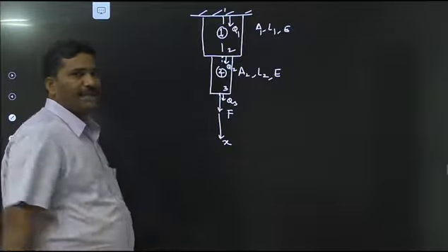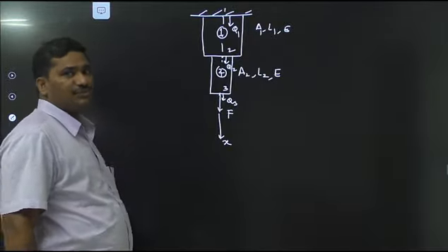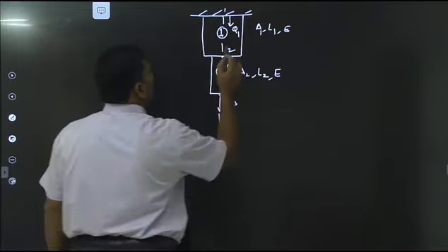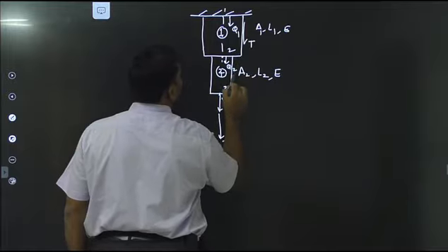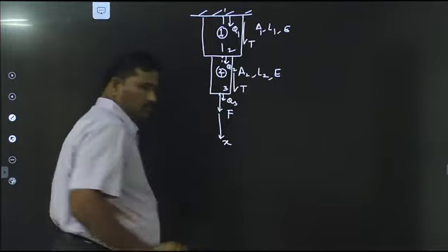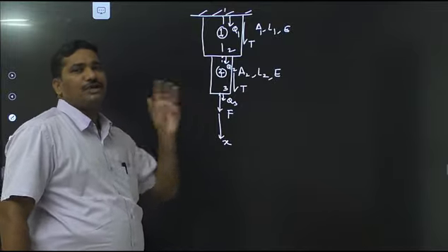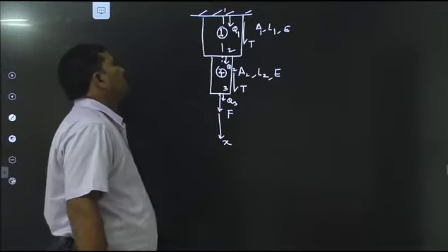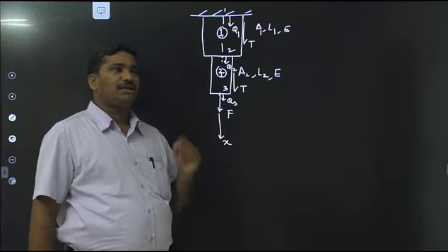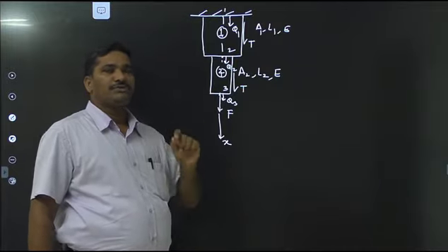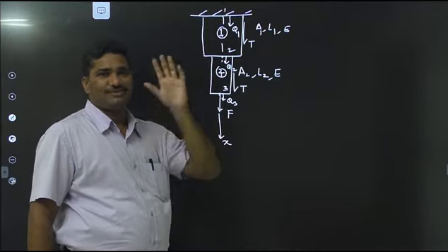Right? Now, traction. I take surface traction. Traction is T. It is written by T. It is the force per unit length. Okay? Now, what is the formula for determining the element traction vector? It is T LE by 2 into a column matrix with elements ones.